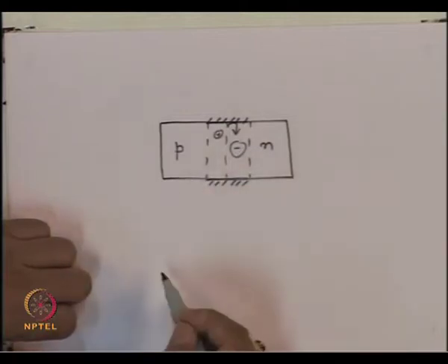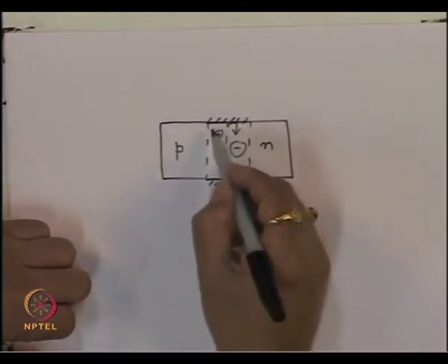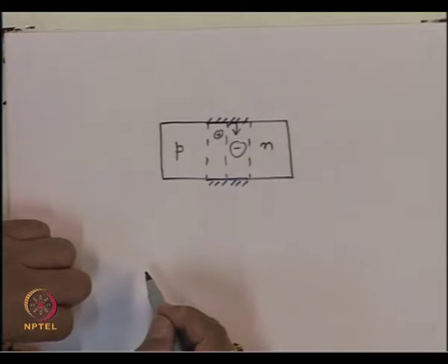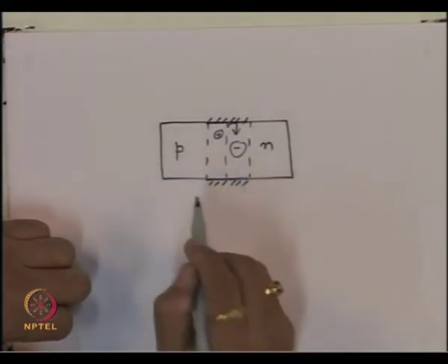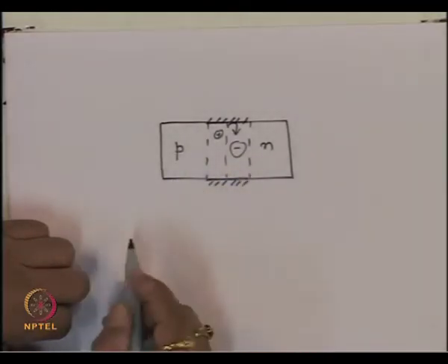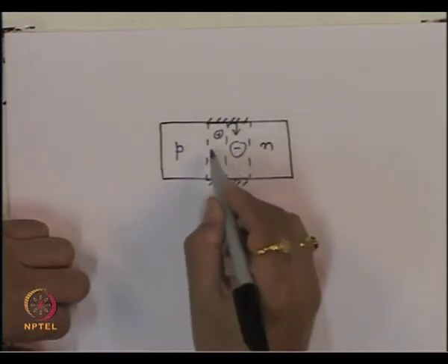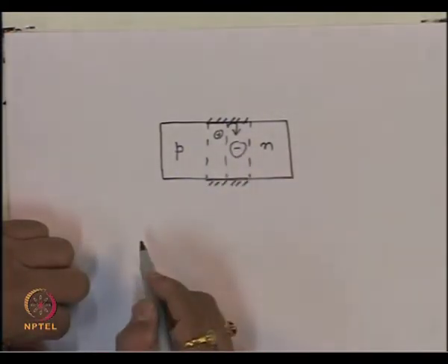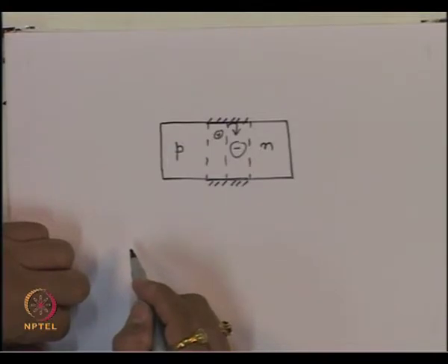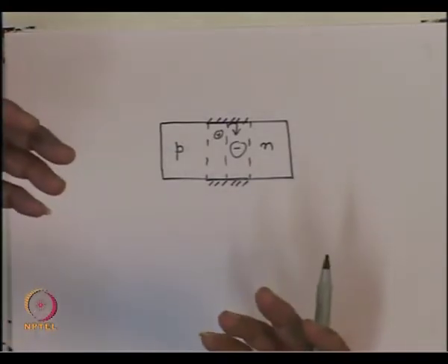So, first thing to note here is that initially when the feedback was not there, as we saw, the efficiency of conversion is very, very small. That means, we have the current which flows into the PN junction, and because of that current the electrons and holes recombine in this region and the photons get generated, but most of the photons get lost and very little light essentially comes out of it. But there was a linearity between the optical power and the current which is flowing inside the device.